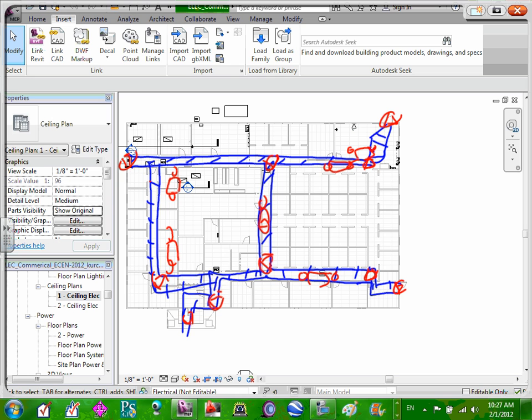The bug eyes are nice because you can see the LED flashing that the battery's dead. Then you, as a custodian or building engineer, know to replace it. Some of the battery ballasts have that same LED, but it's so hidden away that they get forgotten about. So it depends on the project, but we do use them.